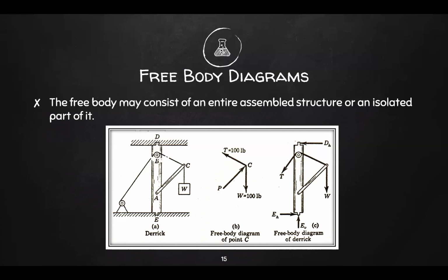To draw a free body diagram, we indicate the forces involved. Whenever you have a cable, rope, string, etc., that usually has tension forces. So we have forces along the wires, and therefore we draw those as tension forces. Tension is always away from your point. That's why it is drawn this way. So we have tension here and tension here. Another thing is we have a reaction force from this pole. That's why we have this force P. So that is your free body diagram at point C.